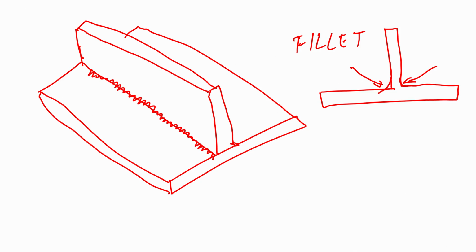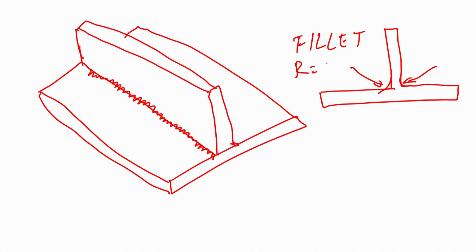Because of stress concentration and because of limitations in fabrication, we need to add these two things. So, if I give a fillet radius equal to 5 millimeters, while this is say 10 millimeters and this is say 12 millimeters, now this is fairly complete, and this is where the instructions are very, very important.